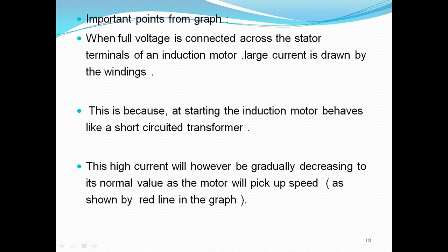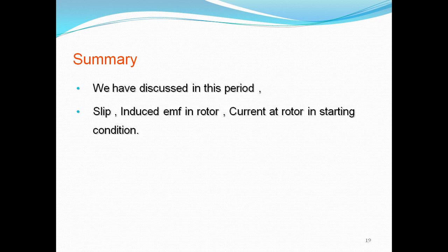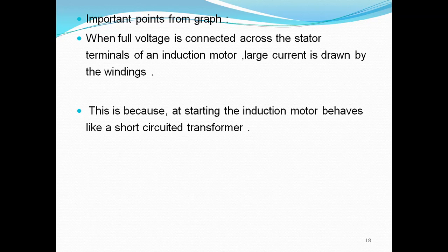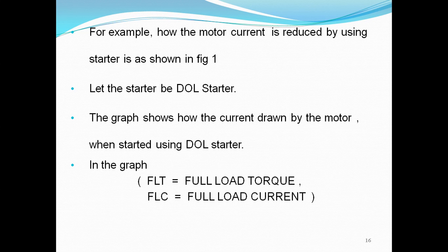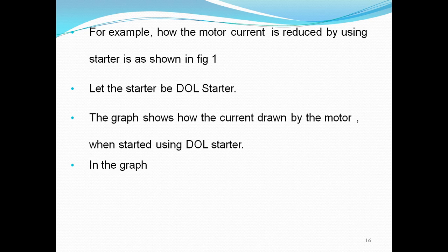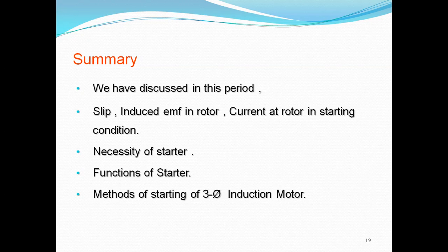When the motor picks up speed and reaches 80 to 90% of the speed, then the starter is disconnected from the supply. So it will come automatically.